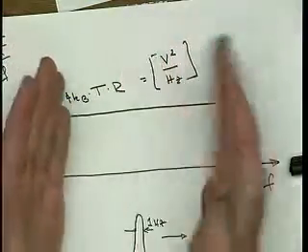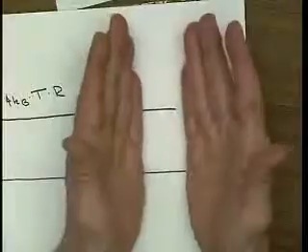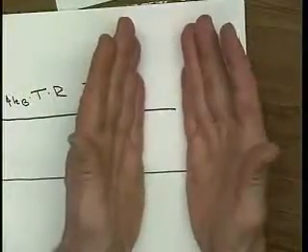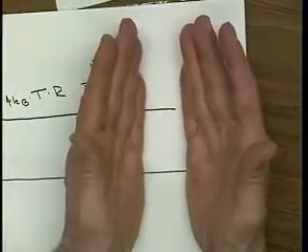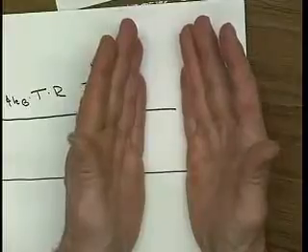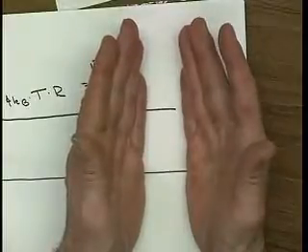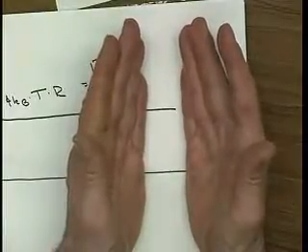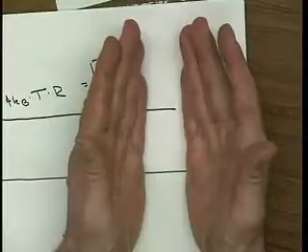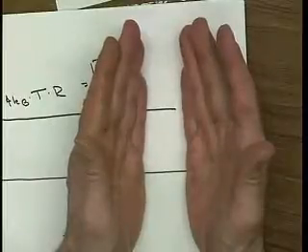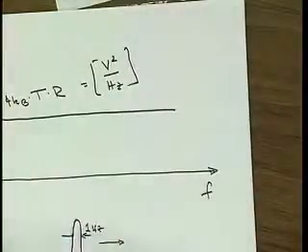But on the other hand, if we had a cellular phone, then it receives at 1 gigahertz, and maybe has a bandwidth of a few 10 kilohertz at that 1 gigahertz. Well, if the bandwidth is the same for our ear and for that phone, it's going to get the same amount of noise from that resistor, assuming that in both cases it's the same resistor that is the source of the noise.